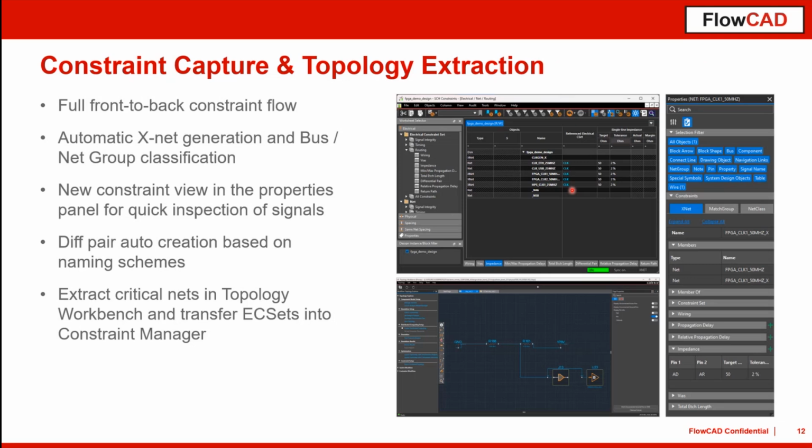One special feature here: constraints capturing, for sure. You have the normal full-blown constraint manager, as you all know. But you also have, in addition, this so-called dock constraint manager. So this is this panel here on the right side. And there you can directly click inside of the schematic canvas, click on the wire, click on the net, and then you see what's going on with this net.